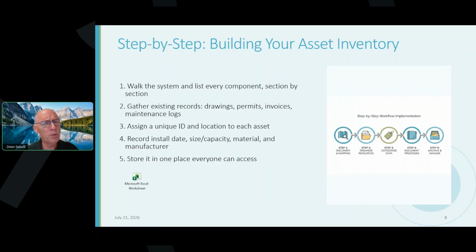As a former drinking water officer, I can tell you that one thing I looked at when I did a water system inspection was, "Okay, can you show me your maintenance logs?" They'd be in the pump house or in the office, recorded on a spreadsheet. These records are gold. If you have lots of them on a clipboard and they're curling at the ends because you have 5 years of it, make sure you get that scanned into your computer or recorded. Don't lose that information, because you spend a lot of time recording things like pH of the water, the turbidity, the chlorine residual, the temperature. It's all there. It serves as a good historical reference.